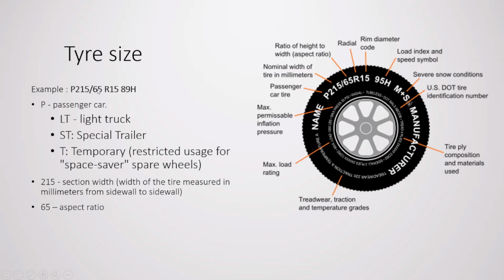So also we have low profile tires, other than the balloon tires. If the aspect ratio is lower, let's say 55, or let's say 45, which means it is 0.45 times the width, with a very low height in the tire.